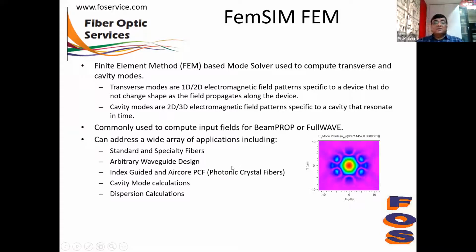The FEMSIM, which is a finite element method-based mode solver, computes the transverse and cavity modes. Transverse modes are 1D or 2D electromagnetic fields, and cavity modes are 2D and 3D electromagnetic field patterns.